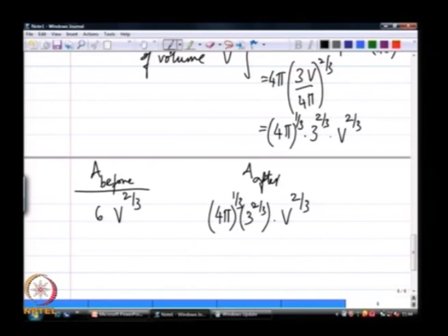You can, with some simple numerical manipulation, see that that has to be greater than 6, is greater than this number in front of V power 2/3. So, the process is heading in the direction of decreasing interfacial energy. So, all other forms of energy remaining the same, temperature, chemical energy, say, I do not know, if there is some spontaneous reaction also happening, interfacial energy alone is decreasing, which is sufficient to make it a spontaneous process.